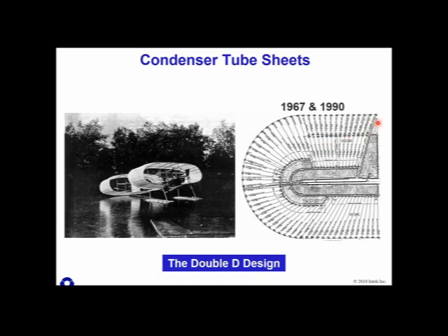This one has a mirrored bundle facing off to the right, so there's no steam penetrating this wall. All the steam comes in from the top, left, and bottom here. And this is the air cooler section for this bundle. It's shrouded vertically and at a slope here. You can see this lane for conveying the non-condensables over into the air cooler section. This one has particular problems with air binding in it as well.